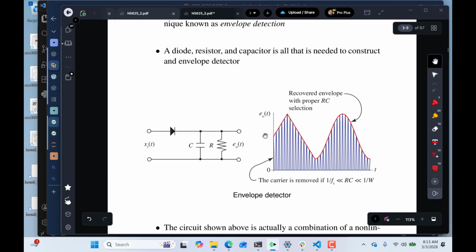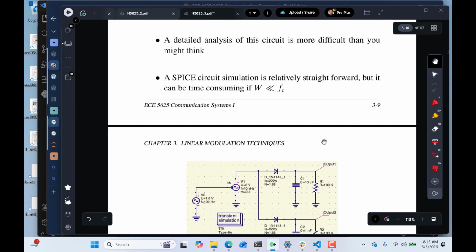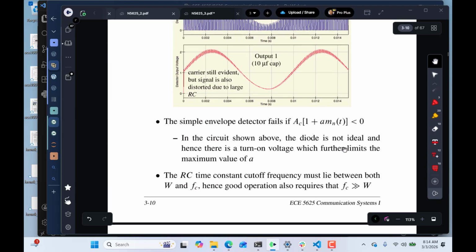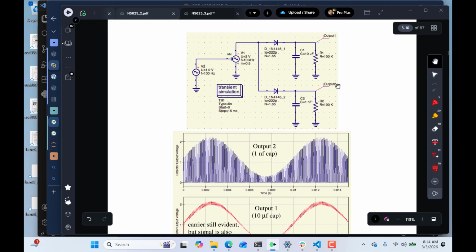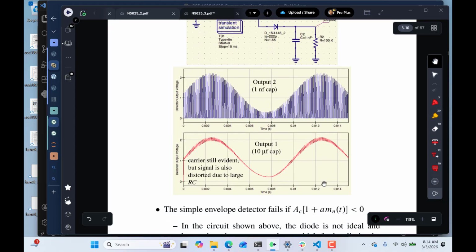So what you would be doing in analog electronics, you'd be coupling this into an audio amplifier that would have DC coupling, so it would remove the bias that's on there. Because once you get it half-wave rectified, you've got it sitting on a pedestal of DC, and you have to remove that. And I showed you the SPICE circuit here, and how filtering attempts to do that. It's hard with a first order filtering action of the diode to remove all of the carrier frequency. But the higher the carrier frequency is, the easier it is.